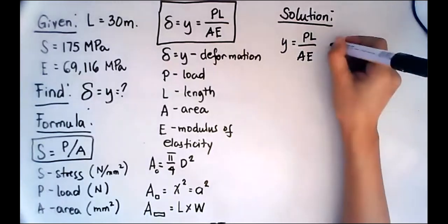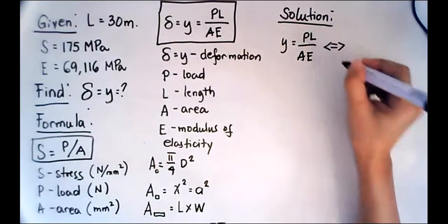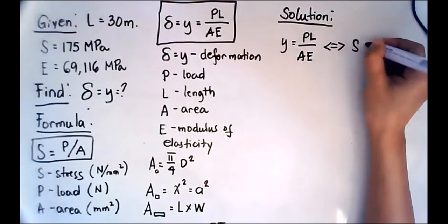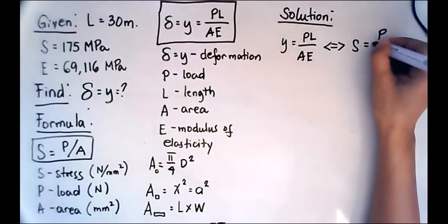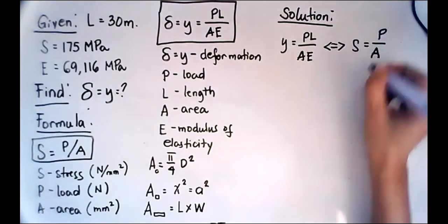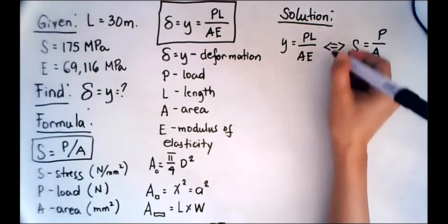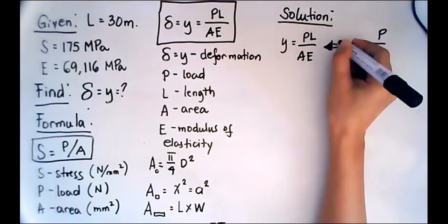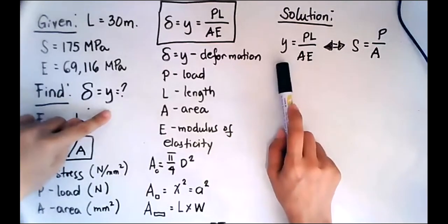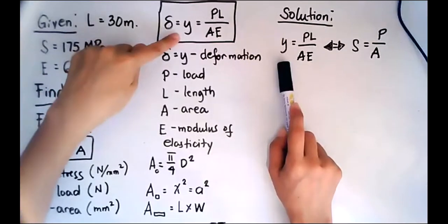And take note also that the formula for stress is equals to P over A. Nakukuha ninyo? Do you follow? Okay. The formula for elongation is PL over AE.